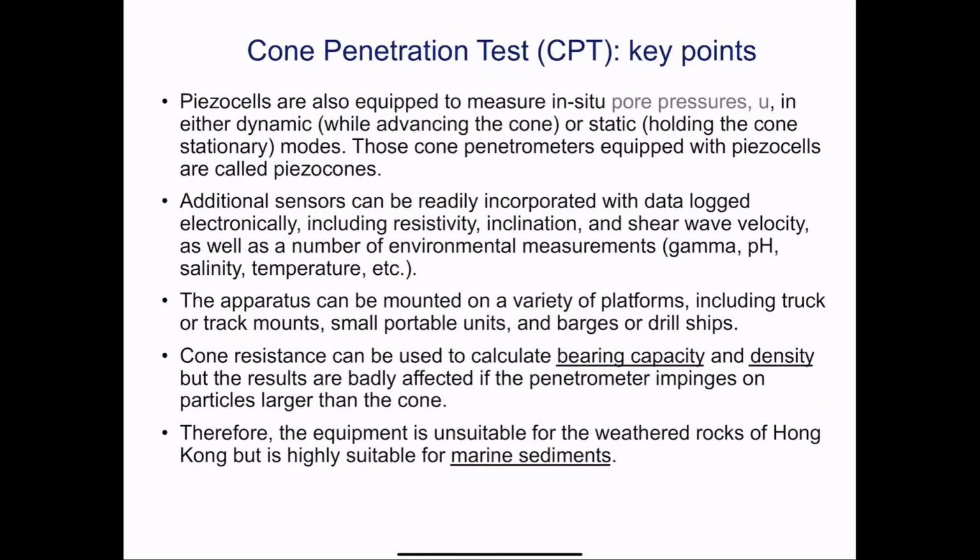Other important points that I want to bring up: there are different names for CPT. If they can be used to measure pore pressure, you might see them called piezo cones as well. Some CPTs that measure pore pressure are also called CPTU. The U is, of course, for pore pressure.